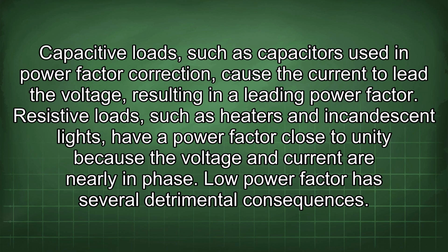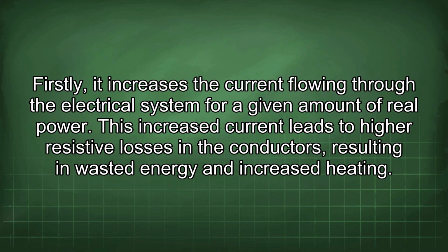Low power factor has several detrimental consequences. Firstly, it increases the current flowing through the electrical system for a given amount of real power. This increased current leads to higher resistive losses in the conductors, resulting in wasted energy and increased heating.